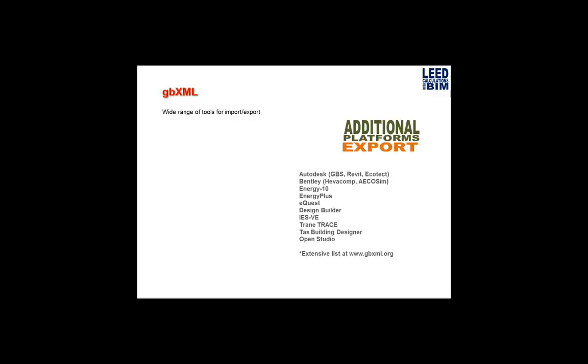So GBXML was originally developed in 1999. It stands for Green Building Extensible Markup Language, and it really acts as a conduit among analysis tools. There's a long list of programs that will accept GBXML for running energy models, and some of them are Autodesk Green Building Studio, Revit, Ecotect, Bentley, Energy 10, some of the DOE tools, EnergyPlus, OpenStudio. Anyway, if you go to gbxml.org, there's a huge list of tools that will accept GBXML.